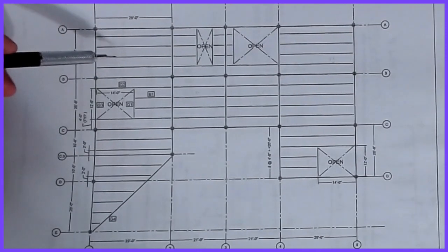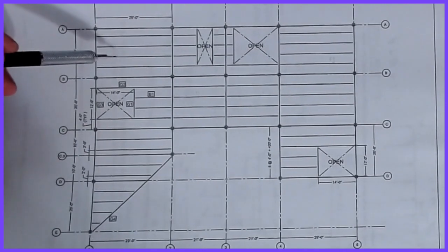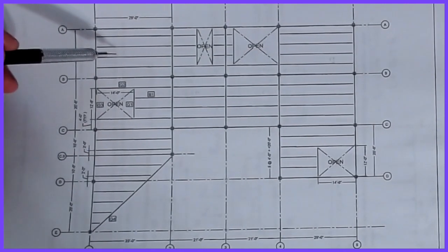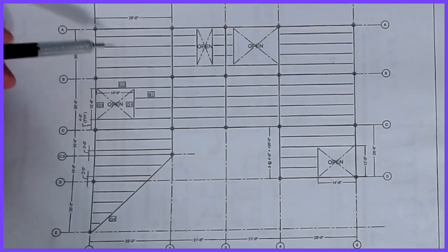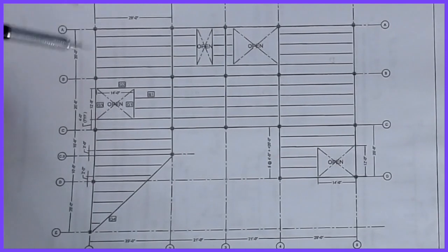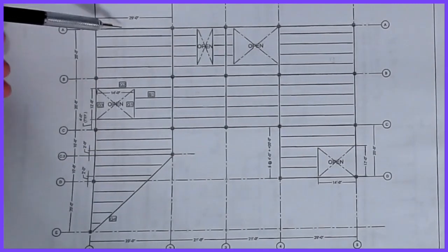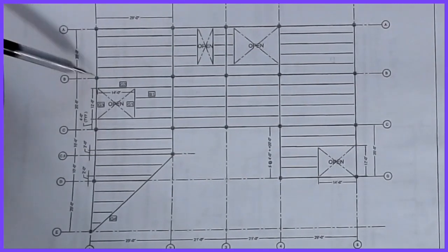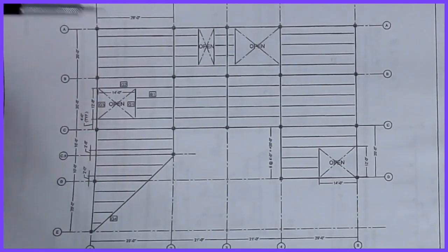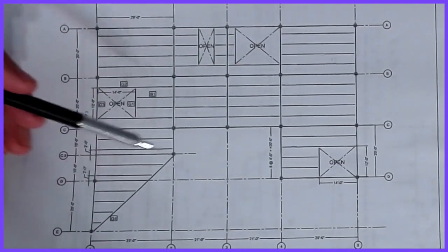If you remember back when you were looking at statics or early structures problems, the loads on a beam are typically measured in something like pounds per foot or newtons per meter. So we've got to get those units of pounds per square foot converted over somehow, and that's where these tributary areas and tributary widths will start to come into play. But we do know that the load on this beam will be different than the one on this one, and the load on this girder is different than the one on this, and the load on this column is different than any other column in the building, just because this structure is so irregularly framed.